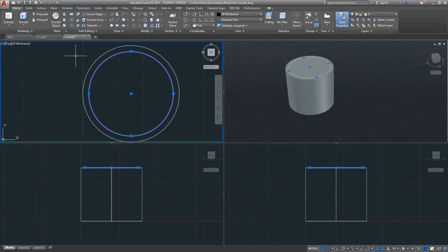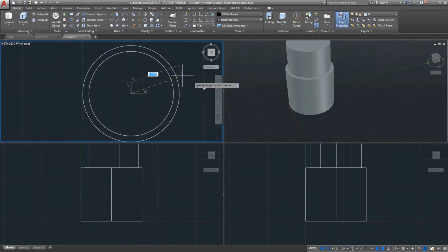There you go. Now, we have a circle here, but we need to make it a 3D object. Extrude is our friend here. Extrude creates a 3D solid or surface by extruding a 2D or a 3D curve, and a circle counts as a 2D curve. Look at the number though, +2, and it's going up.